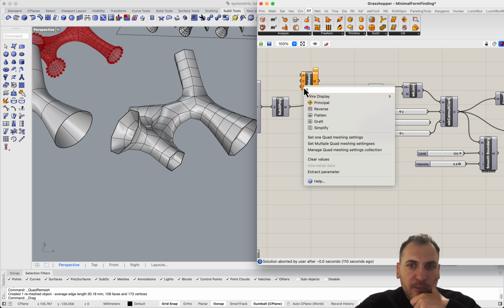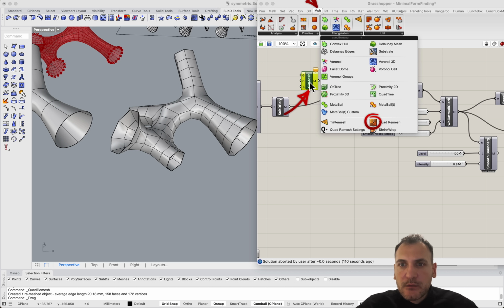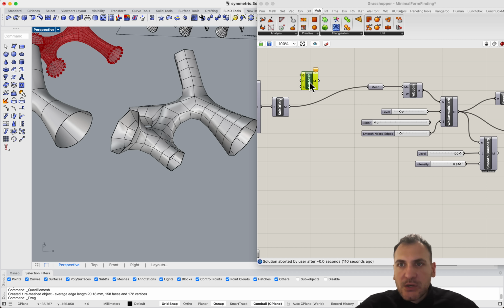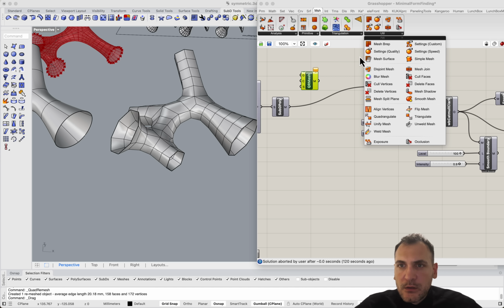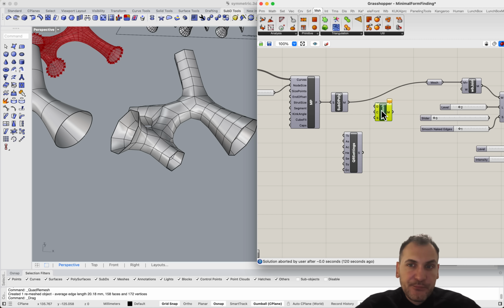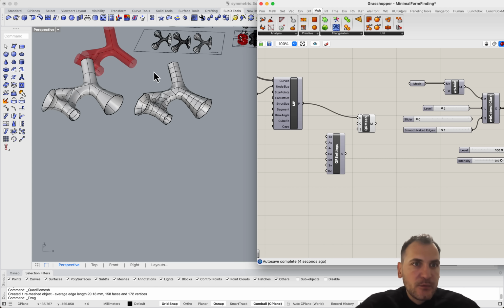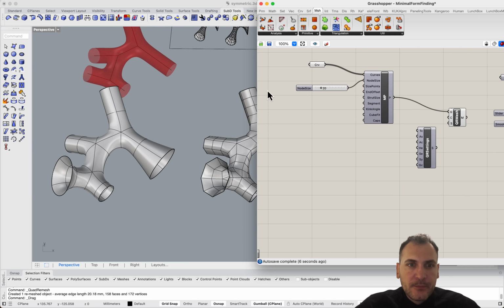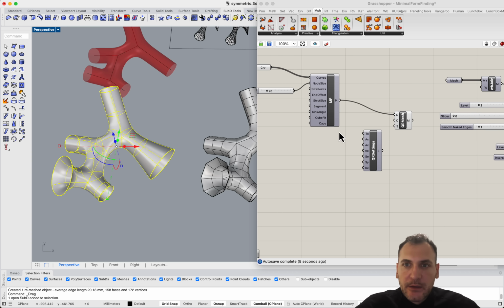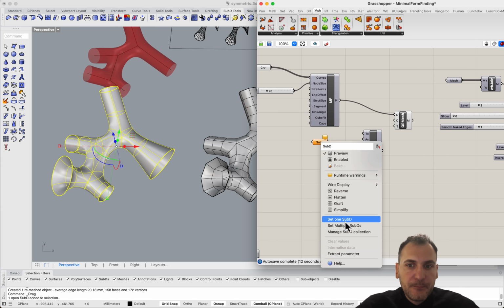target size adaptive. So where is this located? This is located under, okay, mesh, triangulation, quad remesh, and there's quad remesh settings. So I guess you can play around with this. So if I get this guy, delete this one. Let's actually work with this. I kind of like this one better. So we can just load in a sub D.